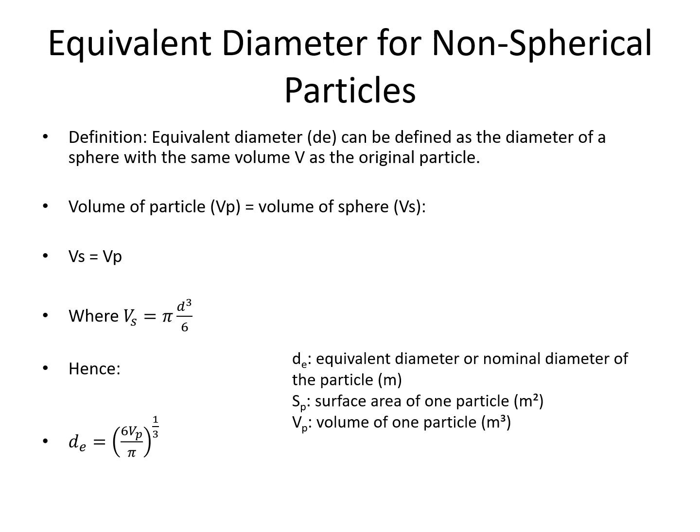The easiest way of calculating is that we equate the volume of the particle to that of a sphere, and we know the volume of a sphere in terms of diameter is in this formula, so we can calculate the equivalent diameter. In most cases we are supposed to find the equivalent diameter of the non-spherical particle, and once we have found it, we can easily calculate the surface area, and we already know the surface area of the particle. In that manner we can calculate the sphericity.